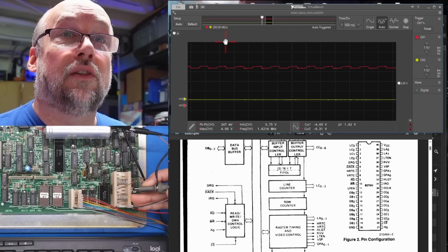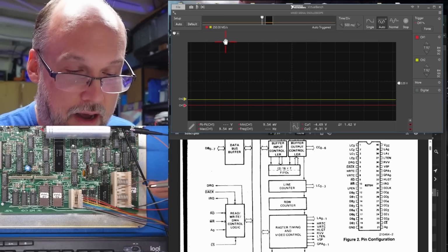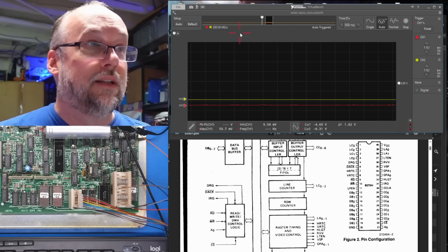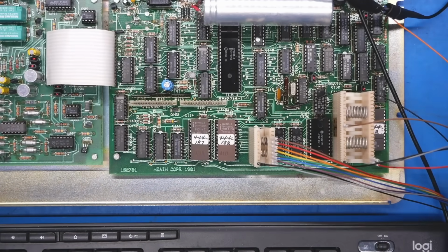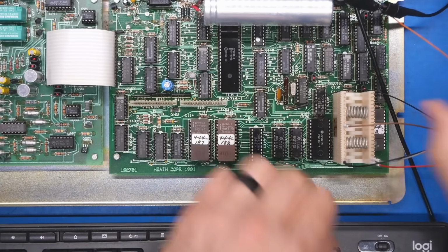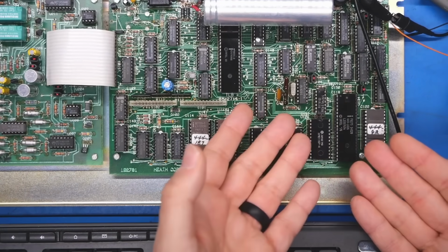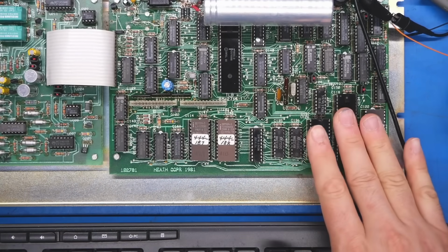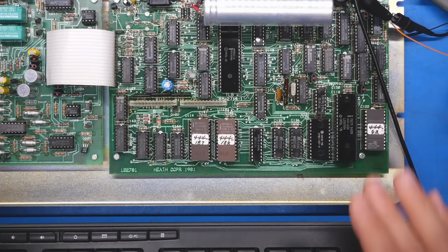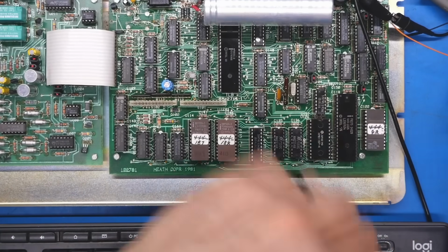Okay, and the next signal is pin 31, IRQ, it's not doing anything. HGLT, that's just low. Yeah, I don't know, there's nothing really coming out of this chip at all. So I kind of feel, let's turn off the power here, I kind of feel that the CRT controller might be bad. I was gonna say, let's take it out and put it back in, put some deoxide in the socket. Could be that. The chip is warm, I know it's getting power.